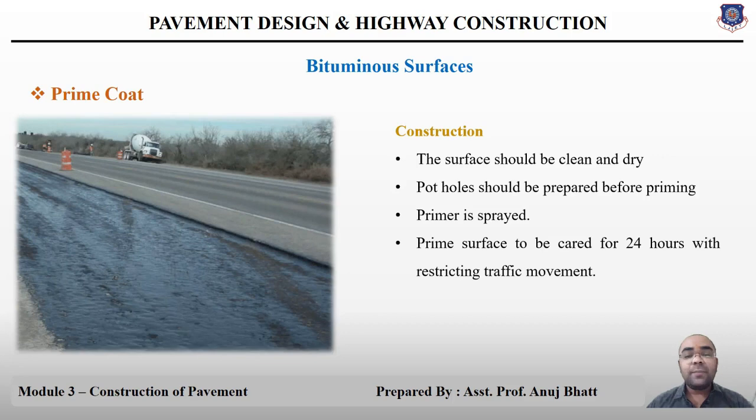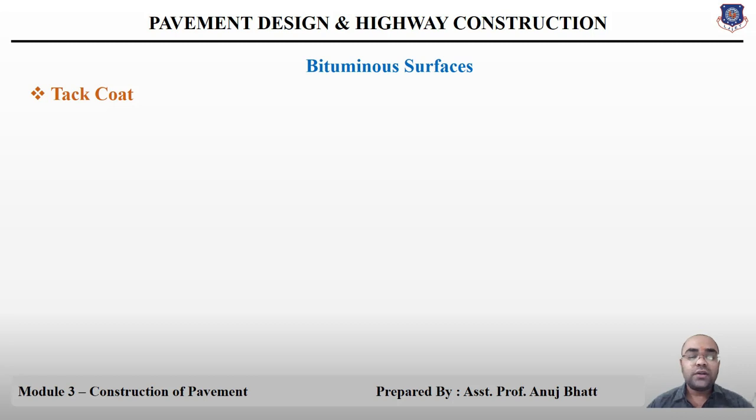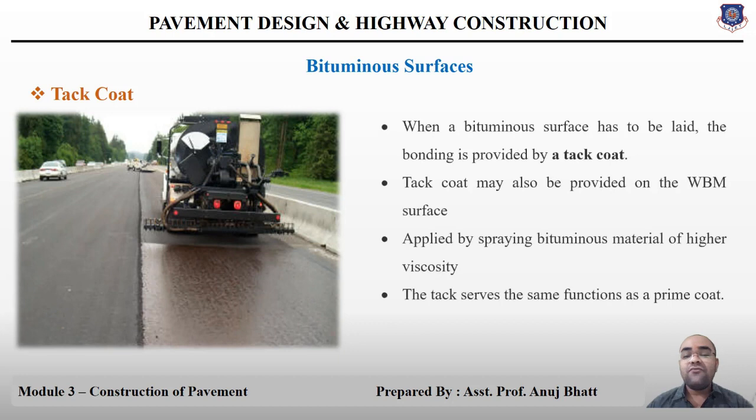So after applying the prime coat, the second is the tack coat. Now for the tack coat, when a bituminous surface has to be laid on an existing blacktop or a cement concrete pavement, then the bonding is provided by a tack coat.